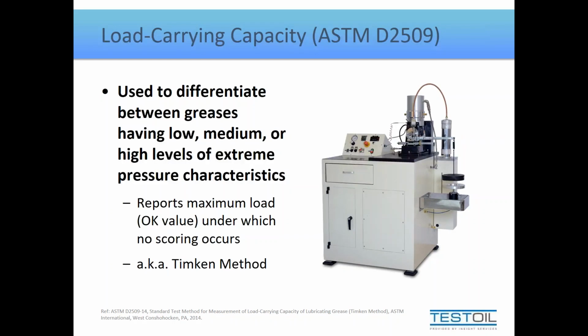So it should be used on greases and/or gear oils. It shouldn't be used on any other products. So if somebody's trying to sell you an engine oil or a hydraulic fluid and doing a demonstration with this, they're pulling your leg. But it is a legitimate test rig. It does have a legitimate ASTM method behind it, and like I said, most people refer to this one as the Timken, as they were the ones who developed it.